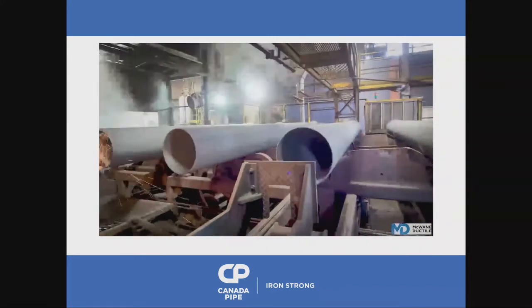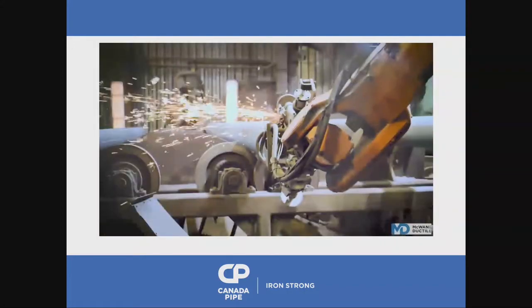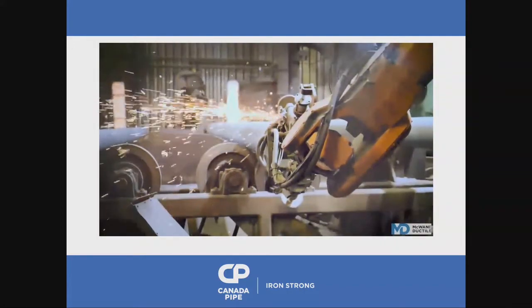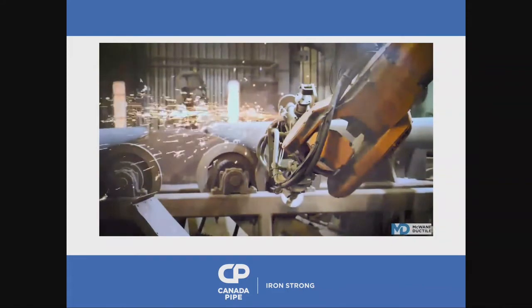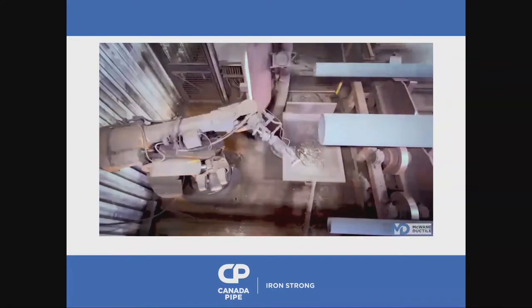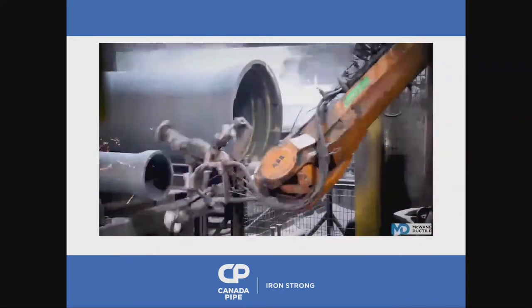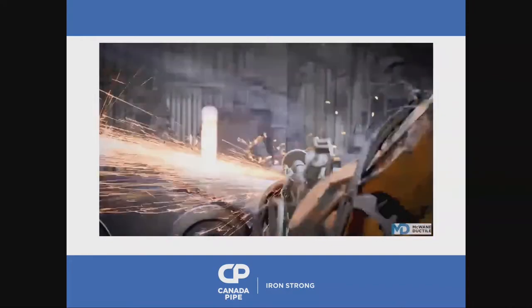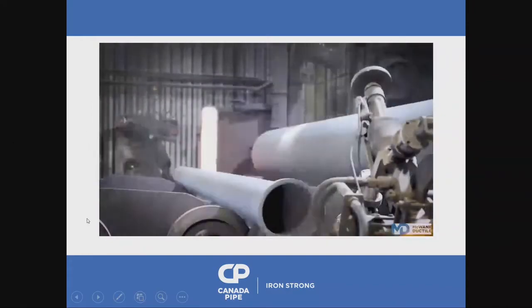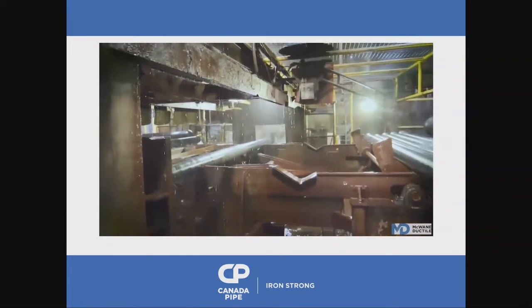And after that testing, we'll test it through the process of hydro testing, where we'll put it up to about 500 psi. Every stick of pipe is tested to 500 psi before it leaves the facility. Now that's the hydrostatic test.